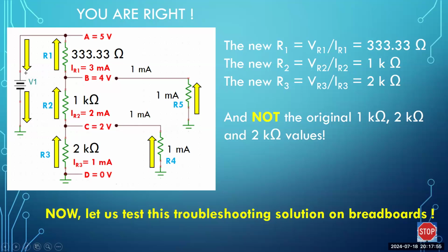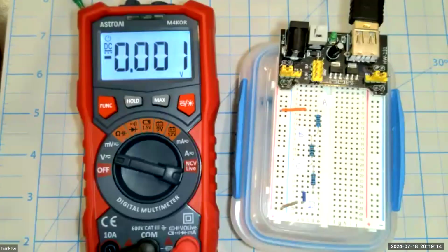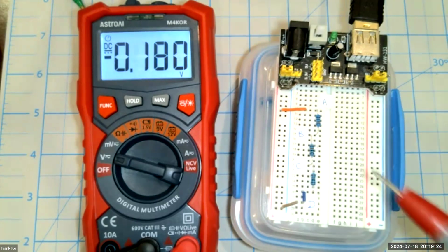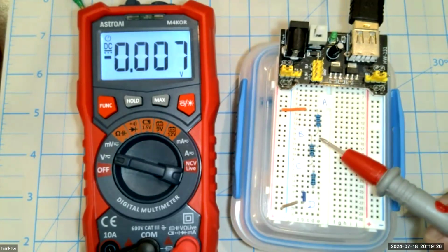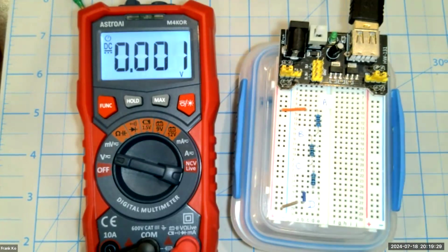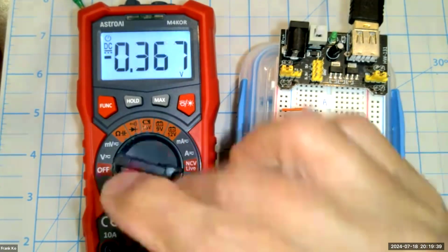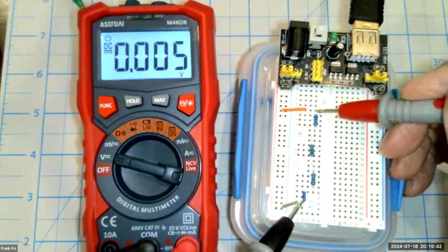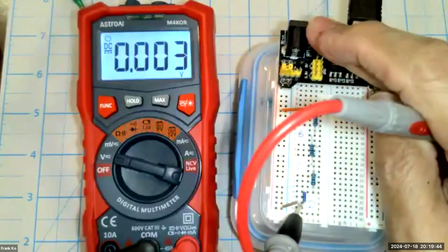Let me put this back on pause and switch to camera mode. All right, in camera mode, we have the voltage divider circuit as we had measured before. We measured the resistances, and we measured the voltages at point A, point B, point C to ground, and across each of the resistors. Not changing anything here because these are the original resistors of the voltage divider. We're just going to double check. This is on voltage mode. Oh, turn the beastie on, that helps.